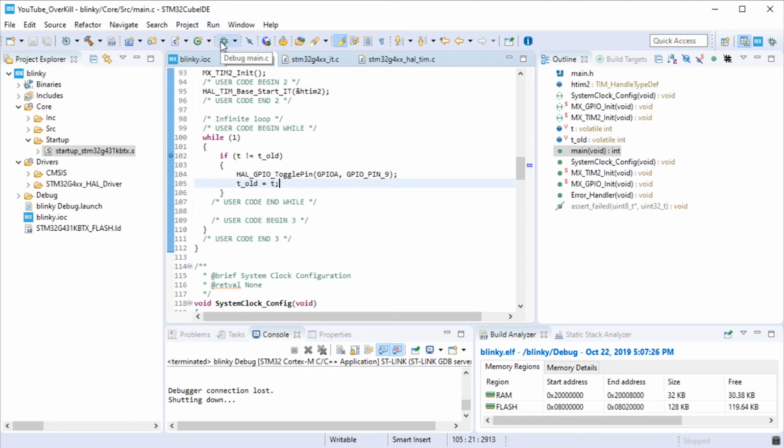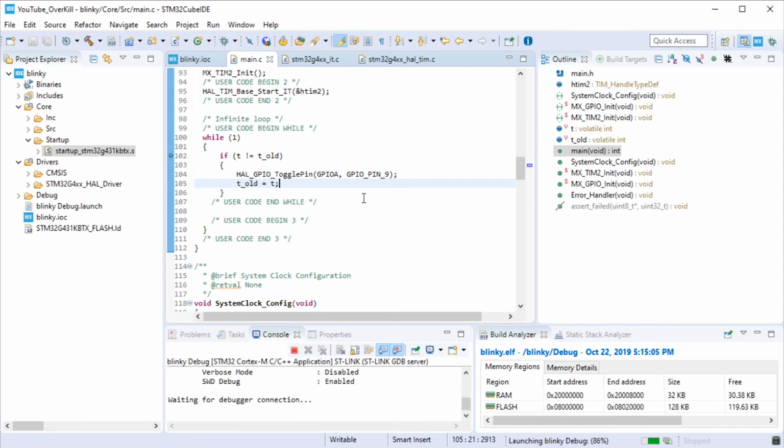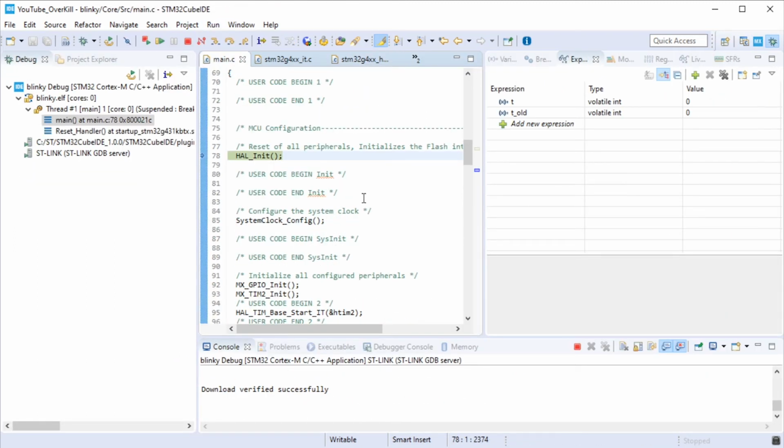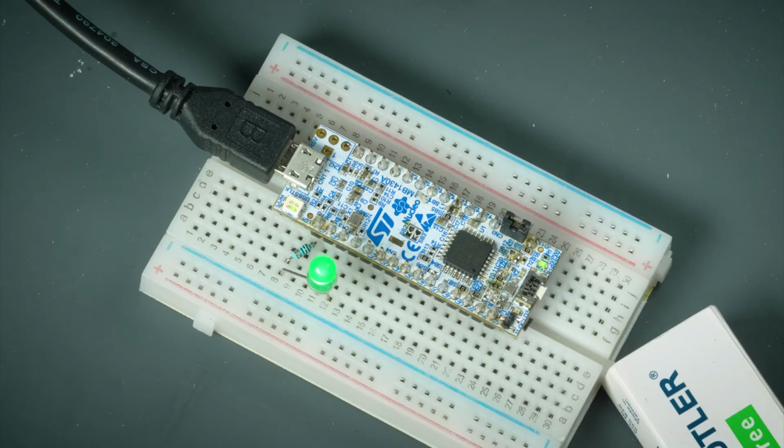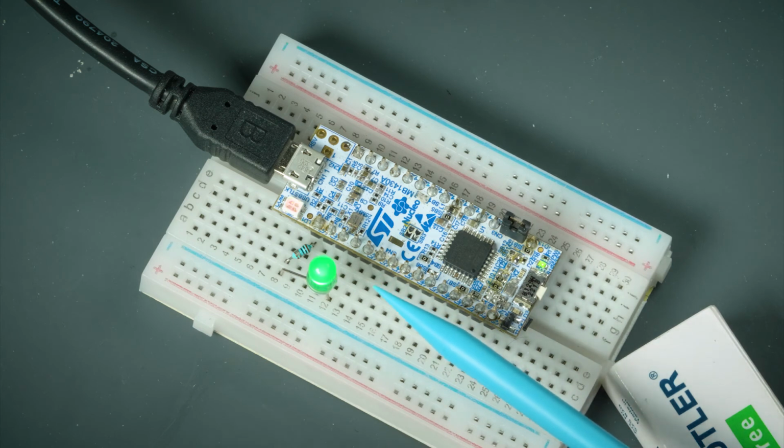So we go into the debugger, we're here again, and now it's the same sort of thing. We still have the same breakpoint as before, so when we hit play, it's going to stop. And we can see, we hit play and we see both numbers toggle now. We should also see the LED lighting on and off. That's exactly what we wanted to see. We can remove the breakpoint, we can hit play, and bingo. Now the thing is lighting just like we wanted, on and off every half second.